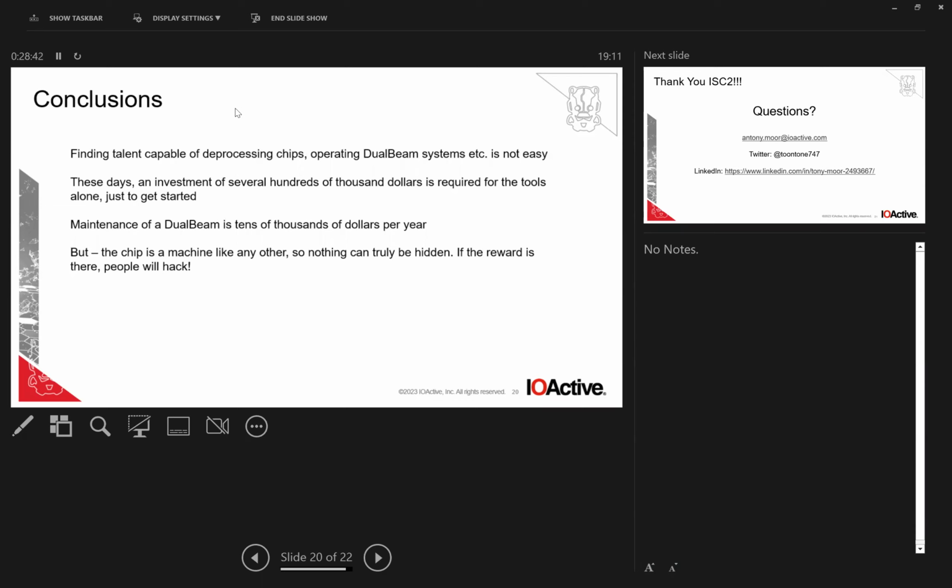You can have a device which is made somewhere by a trusted supplier, but then somewhere along the supply chain, it gets infiltrated with bad material. So on the face of it, it can look like the same package, it can look like the same circuitry, but if you add a small amount of circuitry to this device, it's like allowing a backdoor or allowing somebody to monitor what's going on within the chip.